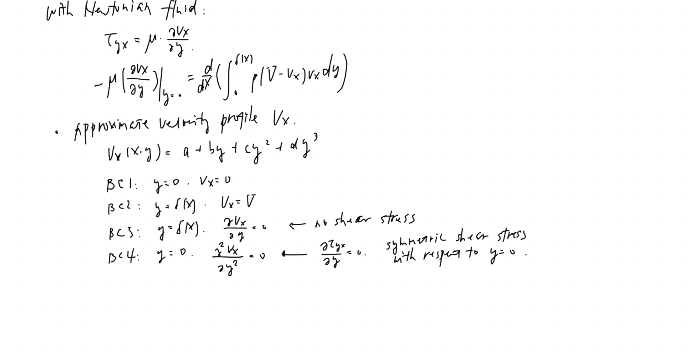Right now, we only talk about the boundary layer on the top of the plate, but it's no harm to assume there is a mirror, that you have fluid everywhere, and then you have the same boundary layer at the lower part of the plate. Then you have a symmetric scenario. So in this scenario, you would have symmetric shear stress. And that's why we have this condition. So this is the mirror image of the condition.